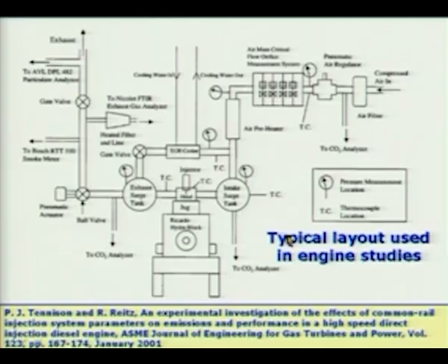So with this background you can see also that we will be measuring the power output of the engine. For example, we may operate the engine at various speeds, and how do you do that? You have to run this engine at various speeds and also allow some of the output to vary by loading the engine. That means that we are going to subject the engine to a load.